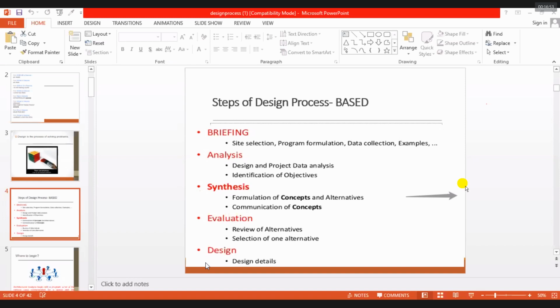While a bubble diagram is a handmade or freehand sketch, a block plan is a single line initial draft of that bubble diagram built in rectangles and squares on AutoCAD. So the bubble diagram is the first step of your floor plan.